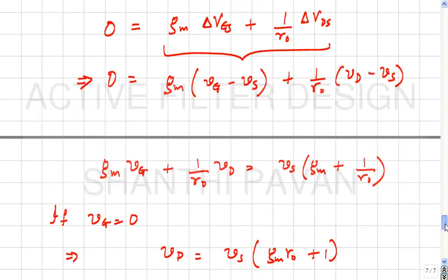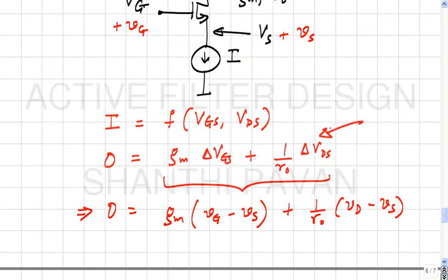Okay. So the intuition behind this equation is that, if the transistor is operating in the saturation region, then a change in the gate source voltage will cause a large change in the drain current when compared to the same magnitude of change in the drain source voltage. Correct? In other words, in saturation, gm rho is a very large number. Correct? So, what is this telling you?